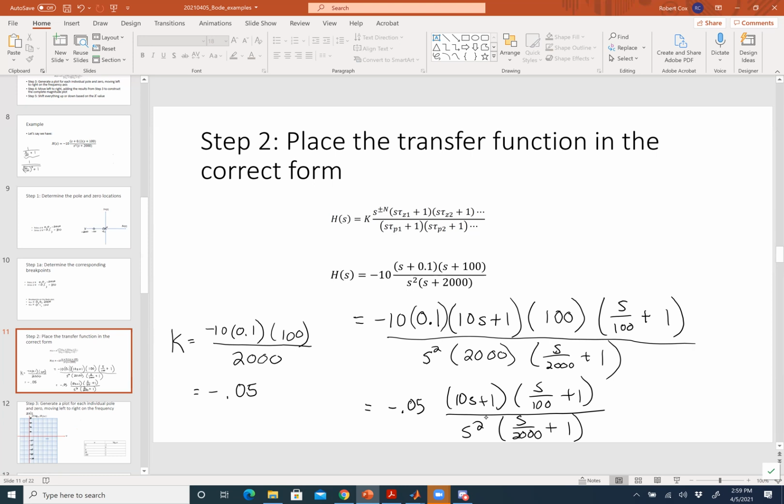In other words, just for sake of argument, if the magnitude at the frequency 100 radians per second is 0.01, then it tells us if we put in 1 volt, what are we going to get at the output? 0.01. If I put in a 1 volt input at 100 radians per second, I'm going to get 10 millivolts out, 0.01 volts out. That's what it tells me, okay? That's important, right? When we're talking about filters and all that kind of stuff, this is a very common way for us to think about it.